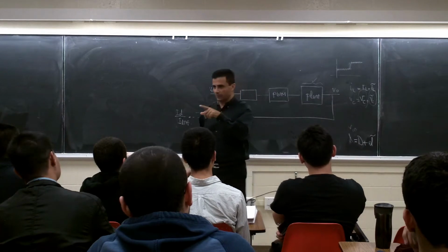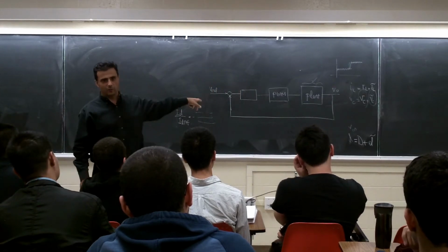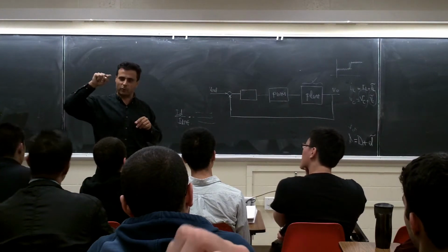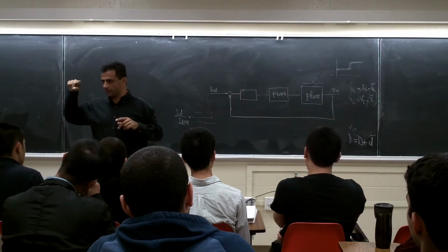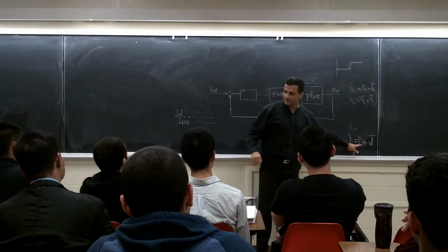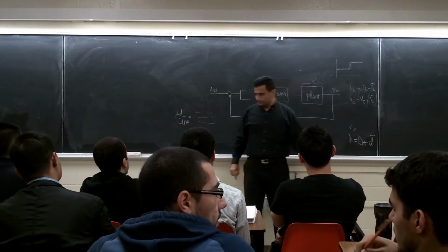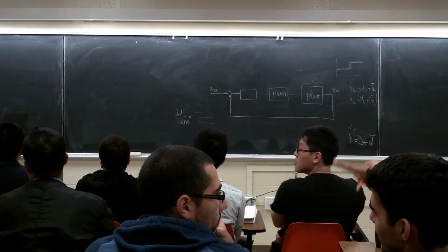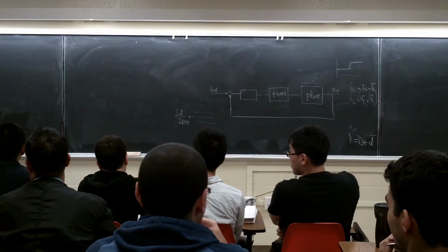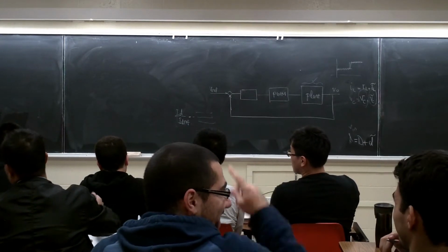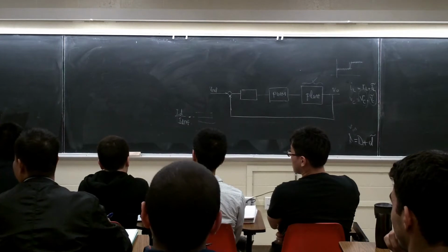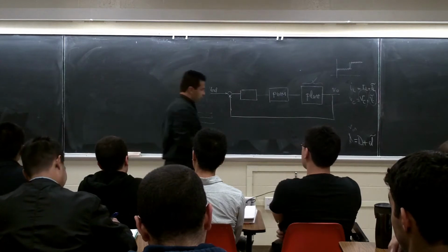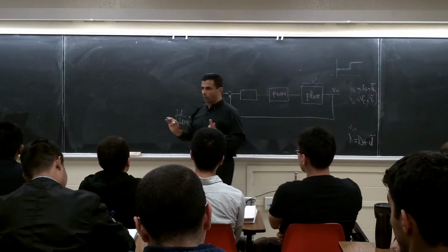Did you simulate the flyback already? Did you look at the D over there? So look at the D. It's not going to be a perfect, for example, 0.8 or perfect 0.9. It's going to be, for example, 0.9 with something on it, right? So again, here, if you see, that's the DC value of the D and the D tilde, right? So let's put it here, a small signal model. I want to find a small signal model of this converter. So, in general, for any converter we have,